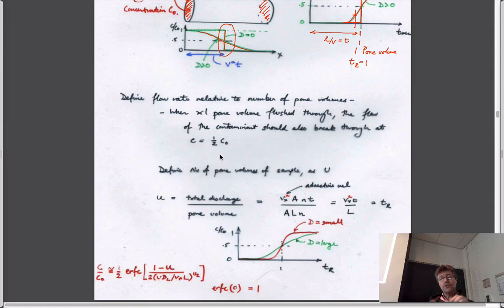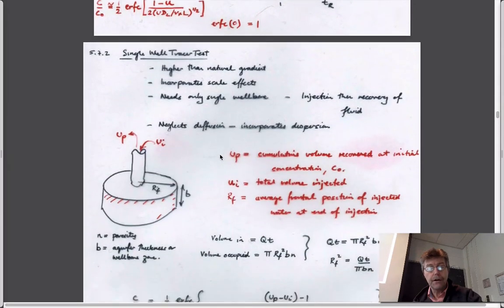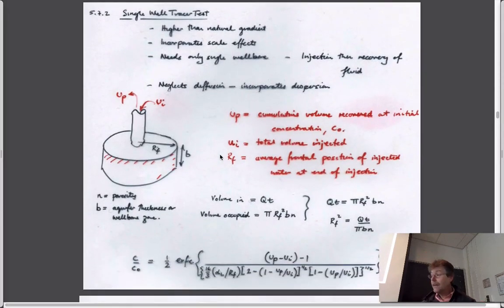And so really what you're doing is you're exercising the aquifer by pulling water out, seeing how quickly it responds, and from the rapidity of that response, by fitting it to a model, you can say what the permeability is because you have a PDE that you're solving. Same for the equations for flow. So for transport, rather, you want to exercise your aquifer by doing something to it.